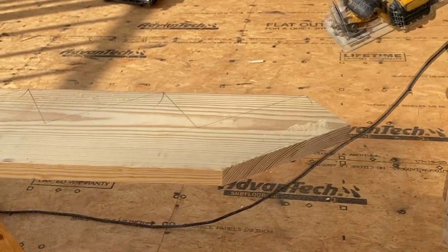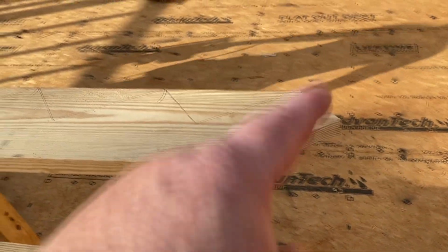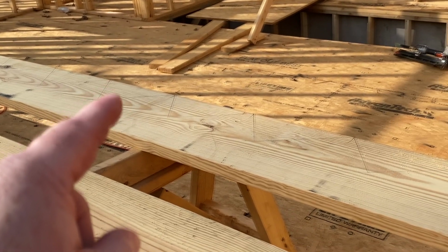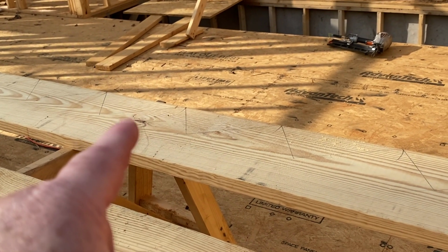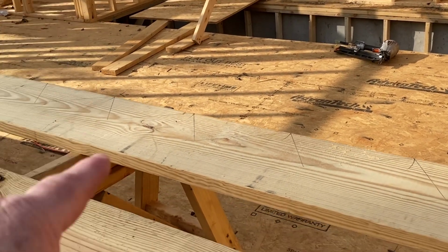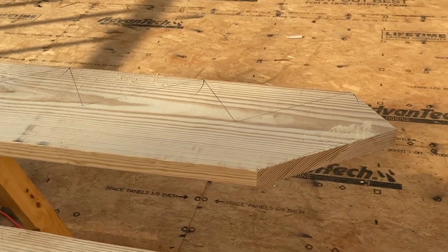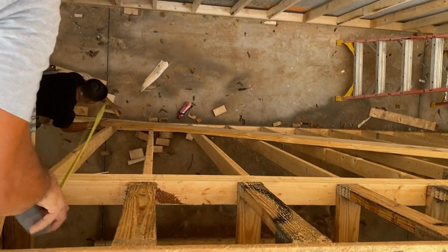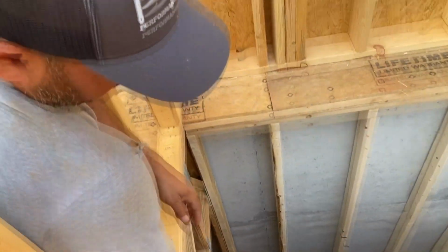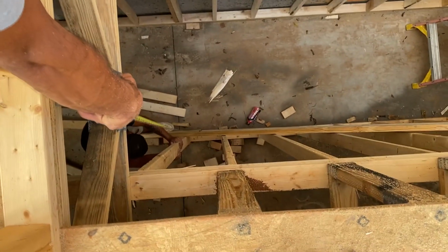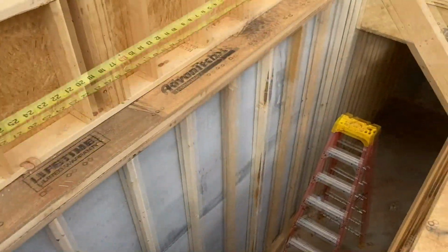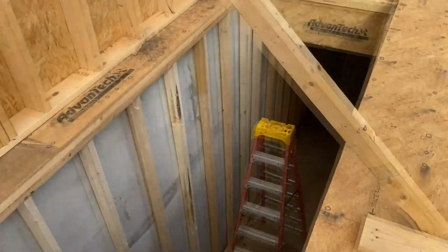So we're just going to cut the bottom and the top, and then we'll test it. We'll also check our headroom at whichever stair is closest to our headroom. We'll measure it to make sure we don't need to adjust anything. Right here, right there. Oh yeah, we got 7 foot and 38. We good. You got 7 foot on that one right there. And it should be about 6'10" by the time we add our Advantech and our tread.